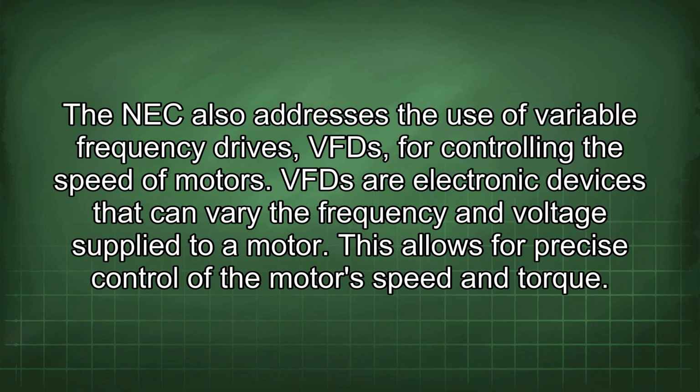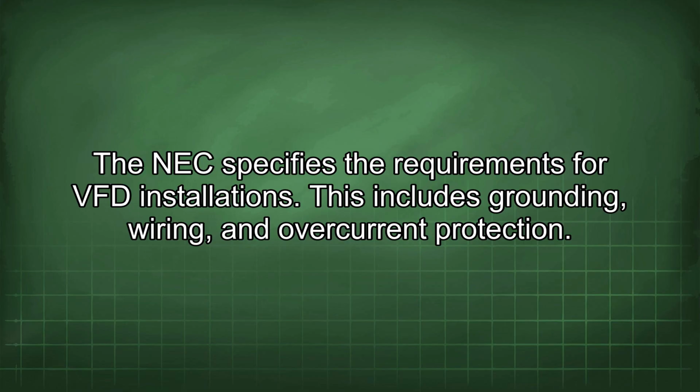The NEC also addresses the use of variable frequency drives, VFDs, for controlling the speed of motors. VFDs are electronic devices that can vary the frequency and voltage supplied to a motor. This allows for precise control of the motor's speed and torque. The NEC specifies the requirements for VFD installations. This includes grounding, wiring, and overcurrent protection.